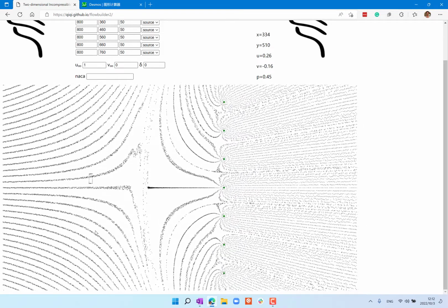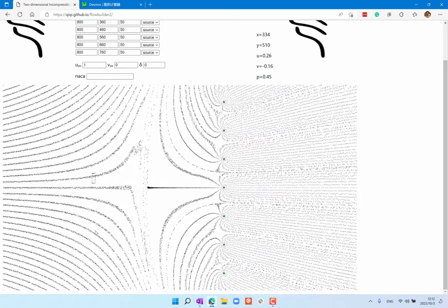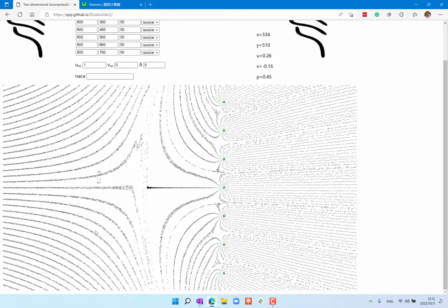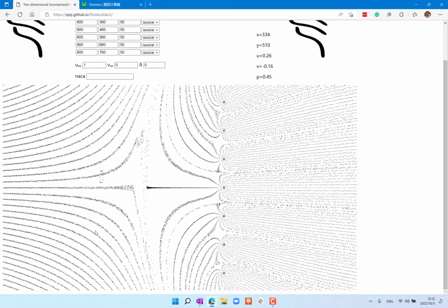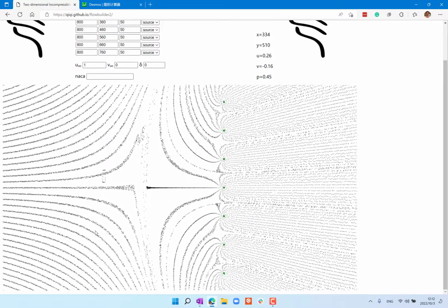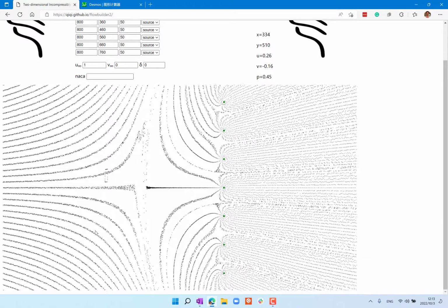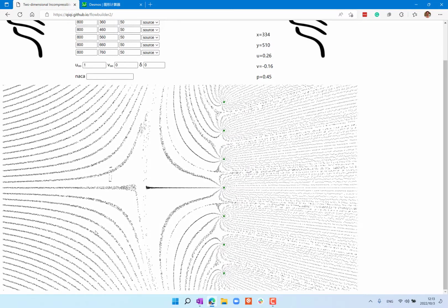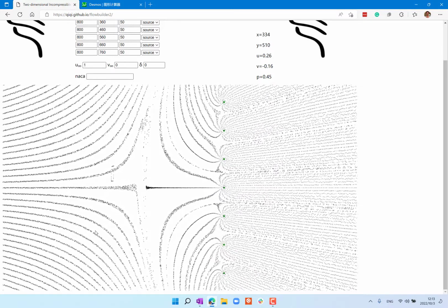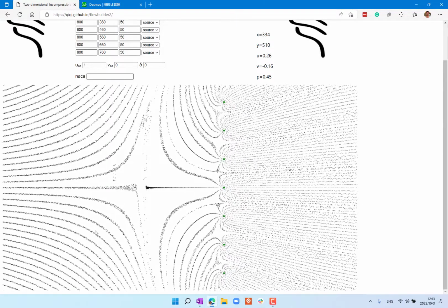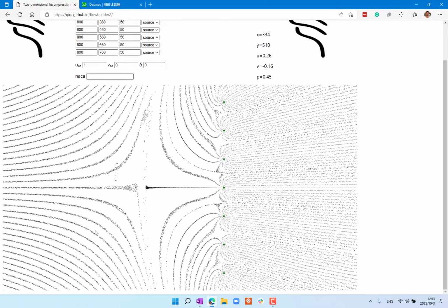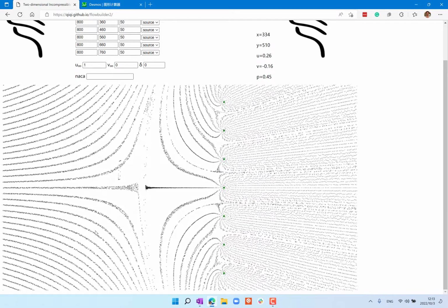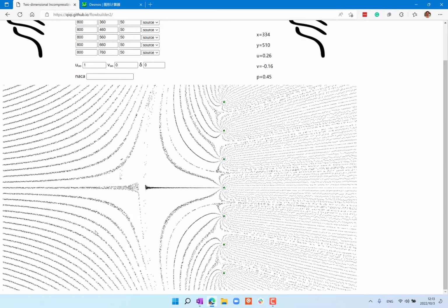Imagine the upper and lower boundaries of the originally square region are the bounds of two streamlines, right? Then as the streamlines widen, this gets stretched. At the same time, we have conservation of mass. So the total area of that rectangle would not change, right? That's because the area is proportional to how much mass is within that control volume, essentially. So this square now gets stretched into a very elongated rectangle.